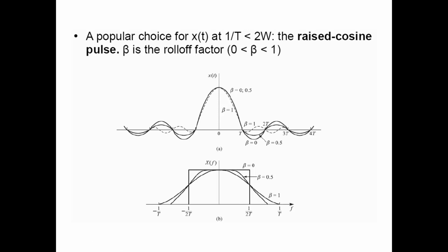And if you further increase the value of beta, what will happen? It will further extend beyond the bandwidth, right? So in that case, you get a better extension of the spectra of all the pulses, and that will lead to the Nyquist condition being fulfilled in a more appropriate way.